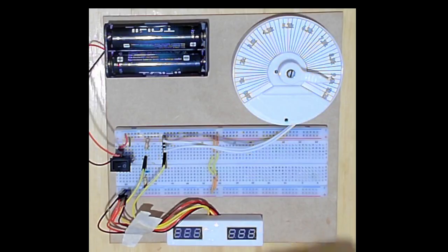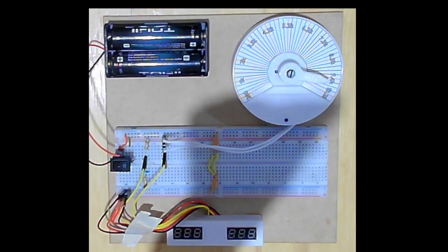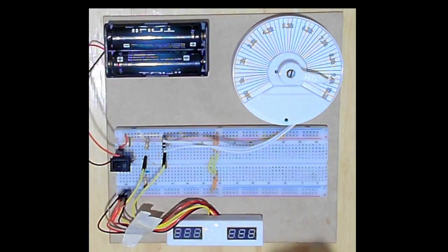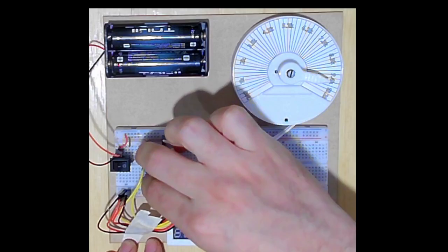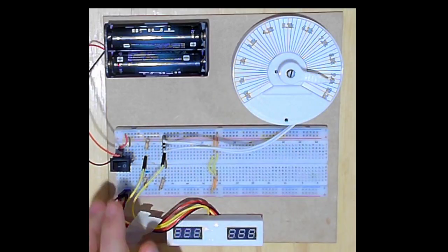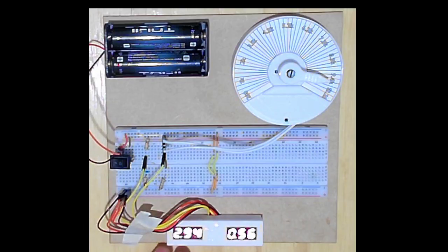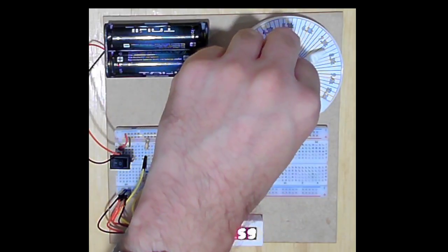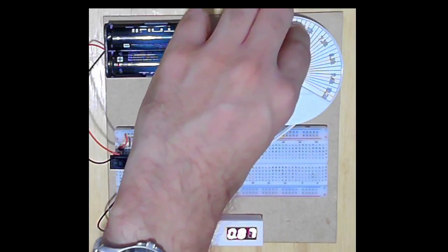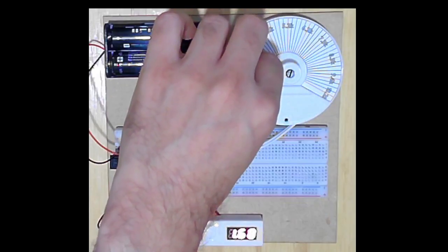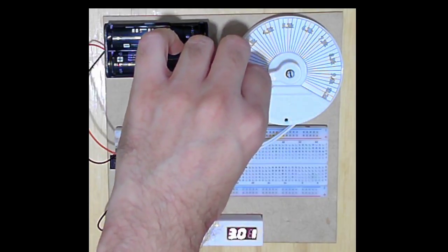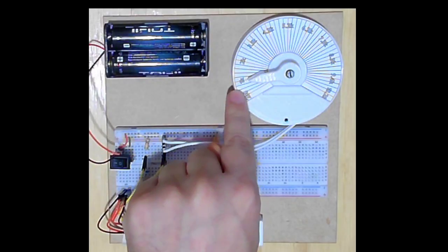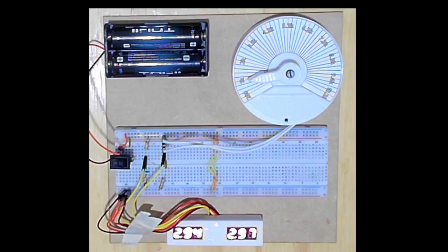Then, for example, this is a brown, black, red resistor. So that's a 1K resistor. If I connect this between R4 and ground, right there, and I turn on, I want to get this voltage to 2.9. We already know that I have to turn, in this case, counterclockwise. So right there, it's in 1K. So that's the correct value, right?